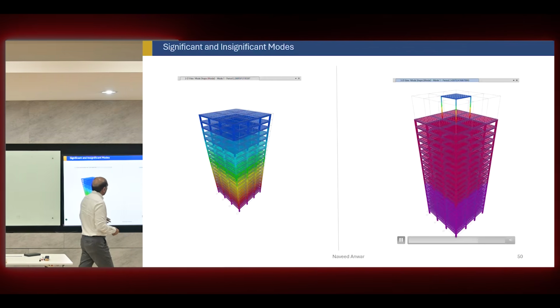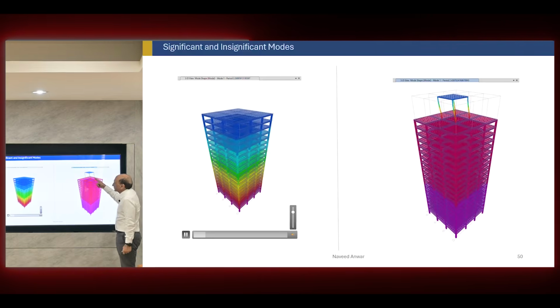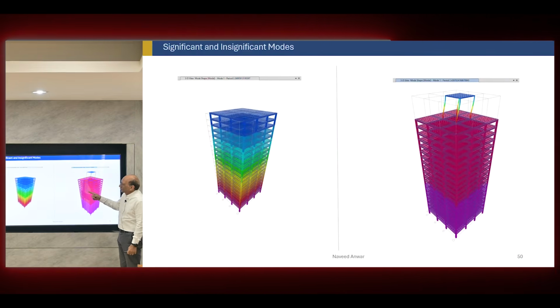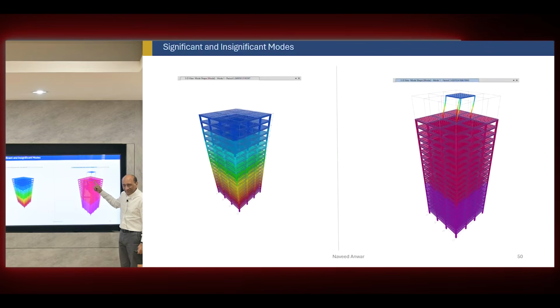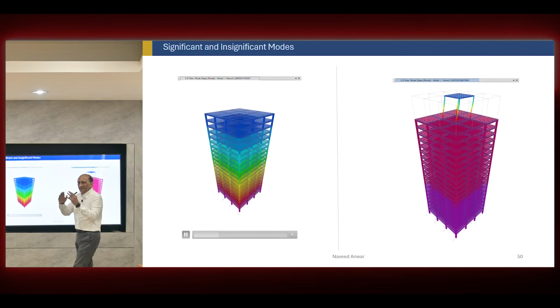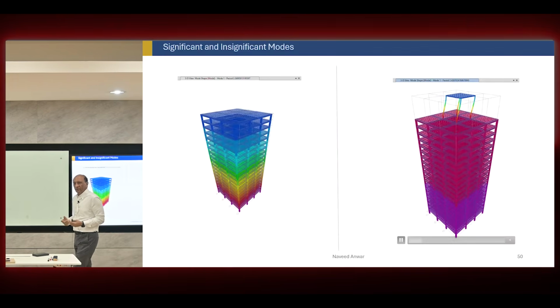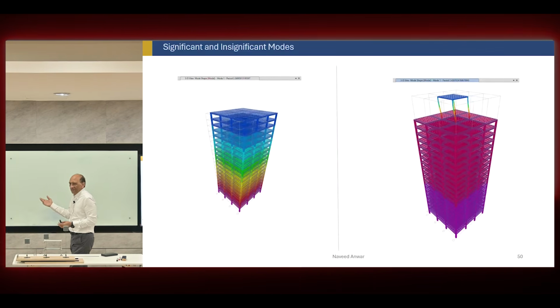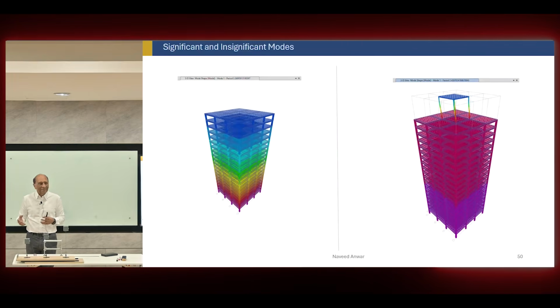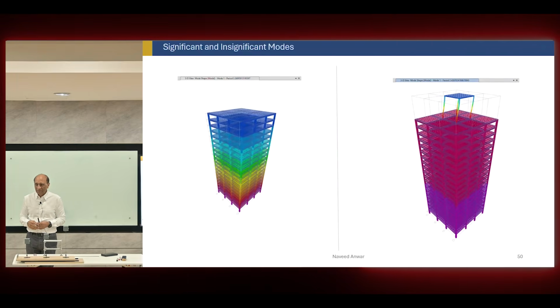So we put a small tower. Many buildings have such towers on the top, as you know, they try to extend it. So if you do a modal analysis with that tower in the model, you will find that the tower portion starts to move first, or the antenna starts to move first. And that will be your first mode. And you'll say, oh, this is not giving me any mass, because normally the first four modes should give you about 80–90% of the mass participation.